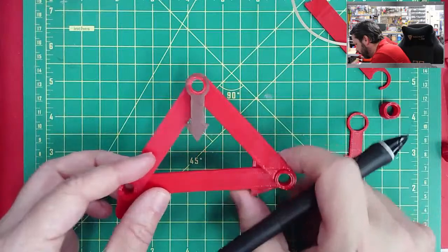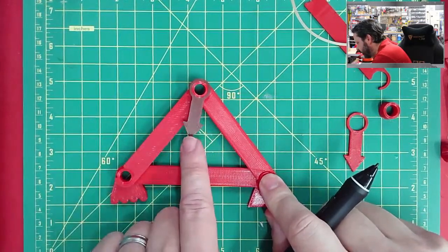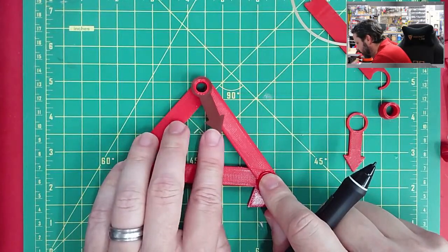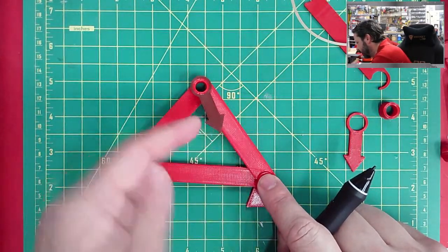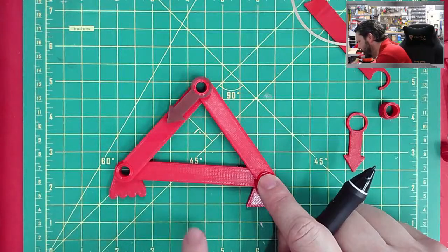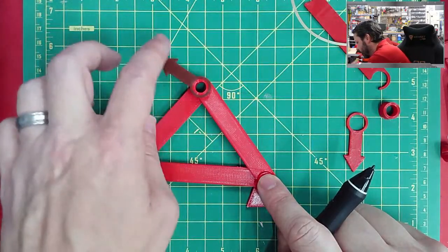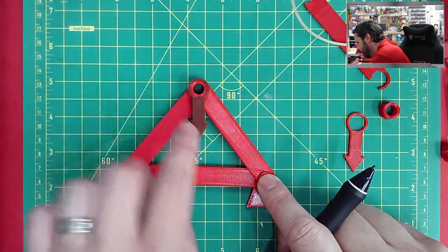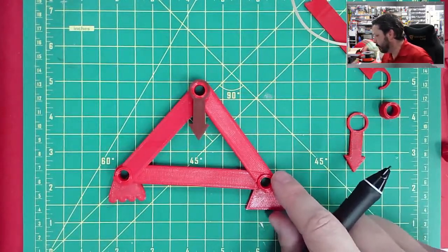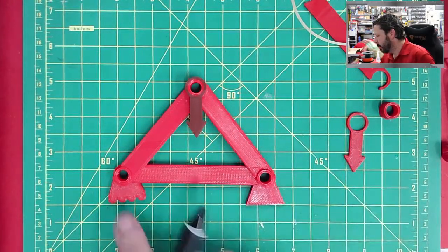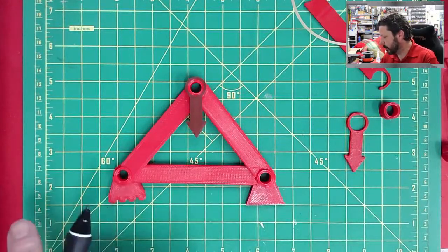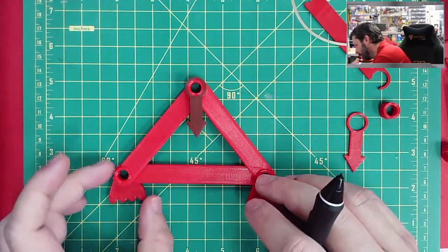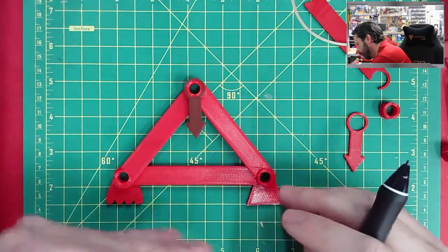If this force had been at some angle, then CX would have a job to do, because it has to react the X component of the force. But if it's vertical with no X component, then this one does not need to react. The roller can't react in the X direction because it's freely rolling on the ground down here.